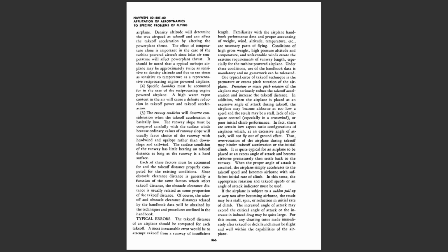One typical error of takeoff technique is the premature or excess pitch rotation of the airplane. Premature or excess pitch rotation of the airplane may seriously reduce the takeoff acceleration and increase the takeoff distance. In addition, when the airplane is placed at an excessive angle of attack during takeoff, the airplane may become airborne at too low a speed, and the result may be a stall, lack of adequate control, especially in a crosswind, or poor initial climb performance.